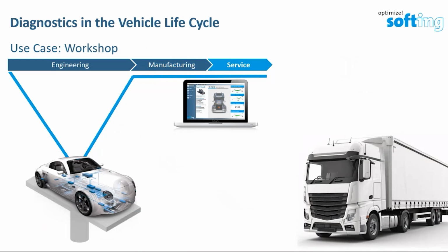So the next use case is in service. It's about workshops. For one part, in the workshop itself, and the other is when the workshop goes roadside for repair. And there are also many different tasks to take care of, like locating errors in the vehicles. We also have repair procedures, and we also have to flash new ECU code and data, read measurement values, and also run inspection routines.